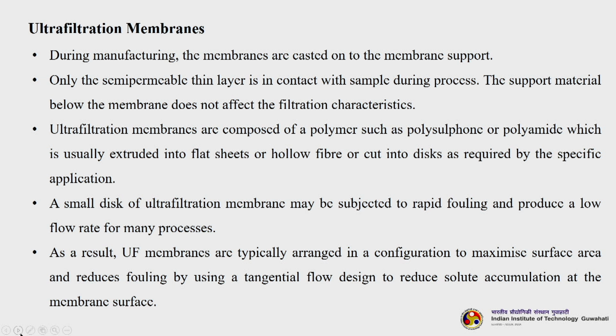A small disc of ultrafiltration membrane may be subjected to rapid fouling and produce a low flow rate for many processes. As a result, UF membranes are typically arranged in a configuration to maximize surface area and reduce fouling by using a tangential flow design to reduce solute accumulation at the membrane surface. That means, most of the times the ultrafiltration membranes, no matter what type of module they are fixed in, are in cascading systems or in series. Today we will see how we actually carry out multi-stage operations.